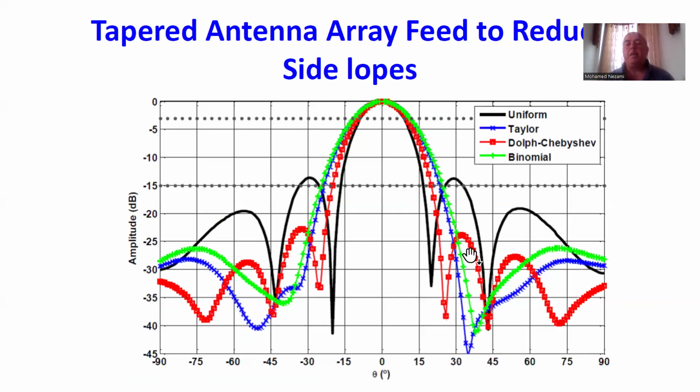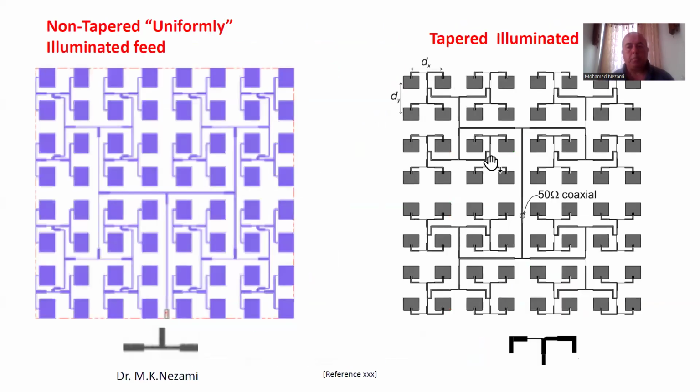The other thing is they reduce the patch interactions. So if you have an array, you have an element, and these side lobes will impact the performance, the impedance, and the loading on the adjacent cells. So that's what we do. Now let's just go through some examples.